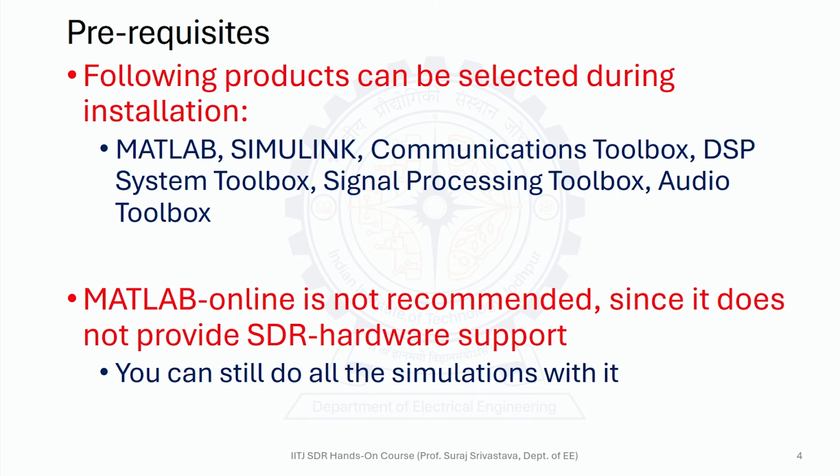In general, MATLAB Online is not recommended because those who will be working with the SDR hardware along with this MATLAB Simulink, MATLAB Online does not support the SDR hardware. That is why we don't recommend MATLAB Online. But still, if you want to do all the simulations, you can use MATLAB Online also.